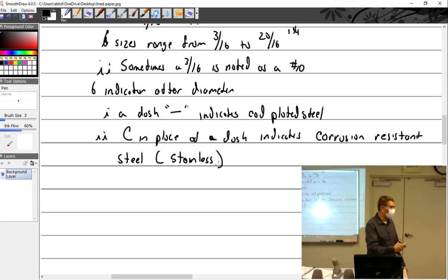Old cad plating, or newer cad plating where the gold wore off. Or aluminum. So how would we know the difference? Magnets. Well, what does a magnet tell me? If it was steel or aluminum. So if it's aluminum, it's not going to stick to the magnet. To determine if it's aluminum or steel, or stainless, or old cad plated.